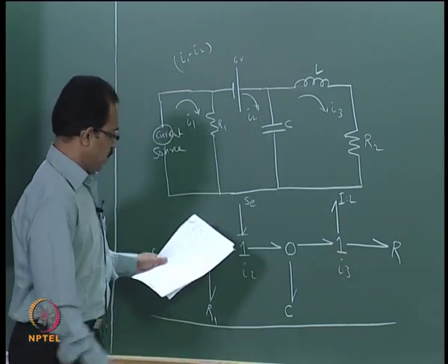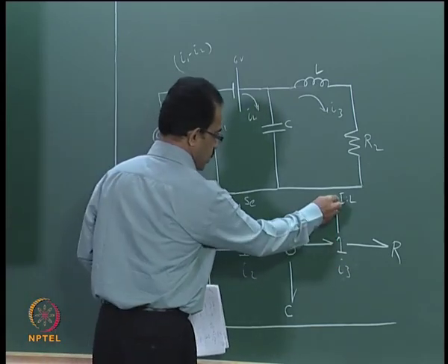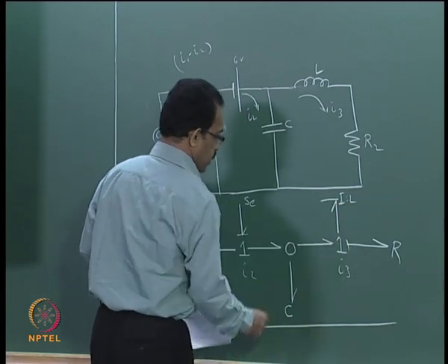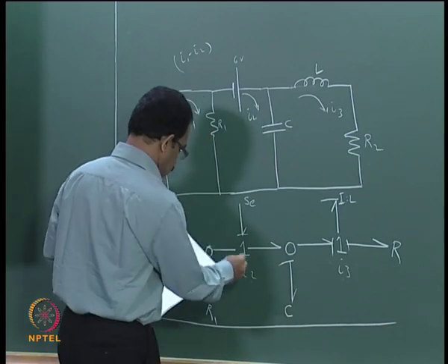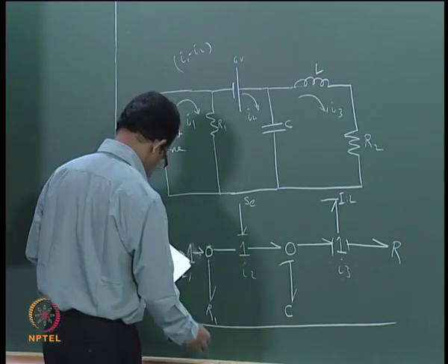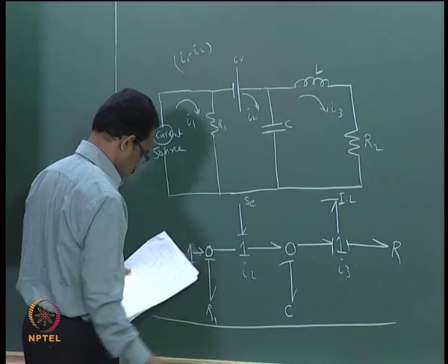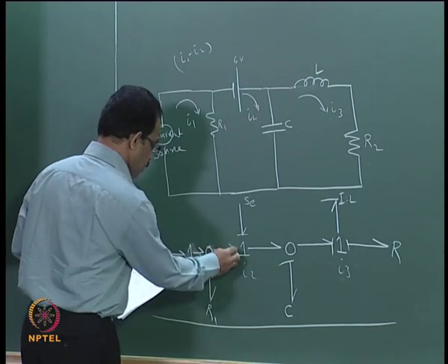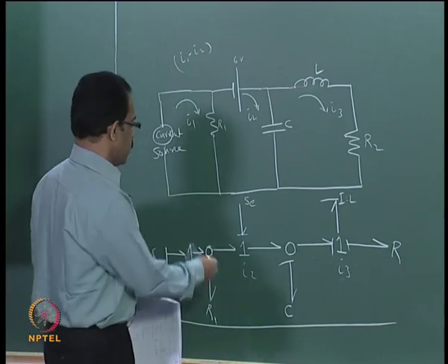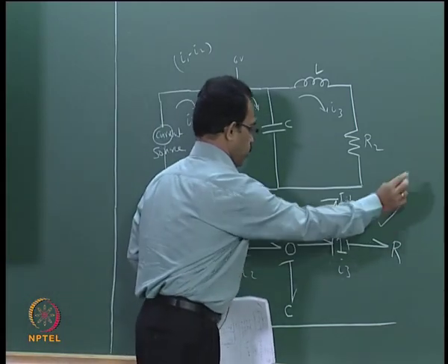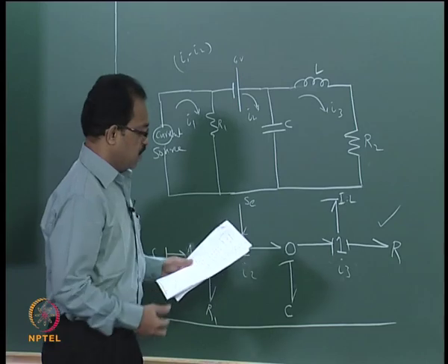And again you can assign the causality here. This is the causality here, and then this is the causality, and the C has got this causality, and SC has already got the causality, and R will be having this causality. This is a one junction, so you will be having this causality here. So this is the way we develop the bond graph model for electrical and mechanical systems.